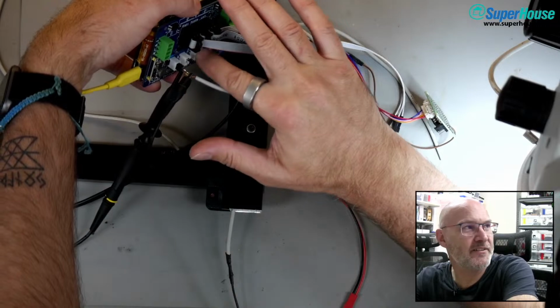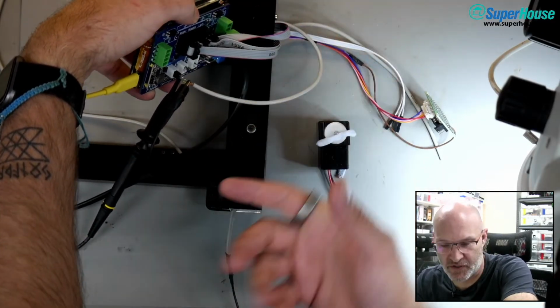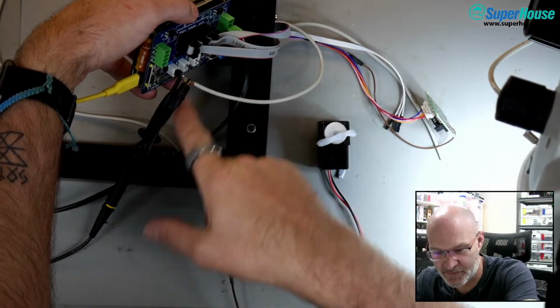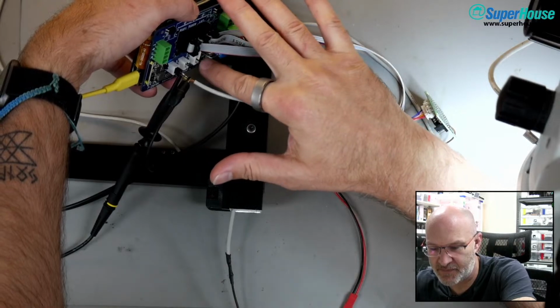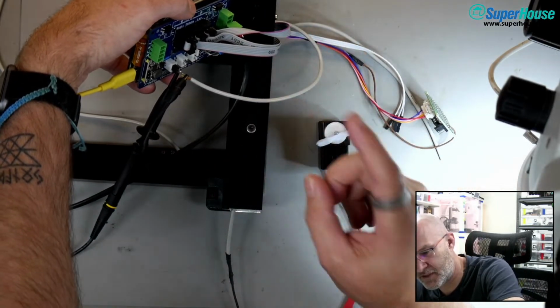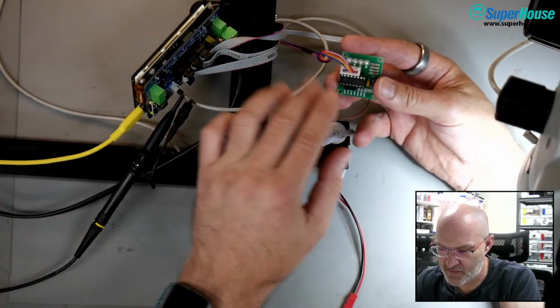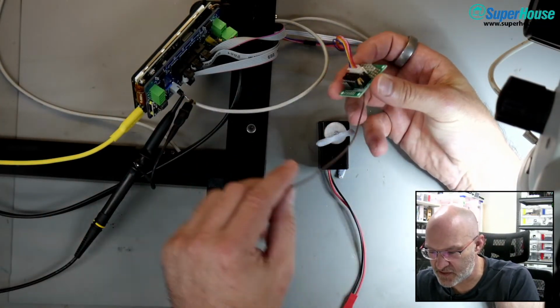Okay, so that white header under there that you can just barely see, it's awkward from this camera view because I've got everything plugged in. USB going that way, I've got stuff going this way, I've got the scope plugged in here. So that is the Y-axis stepper header. It's the 4 pins that go to here, plus ground and 5 volts.